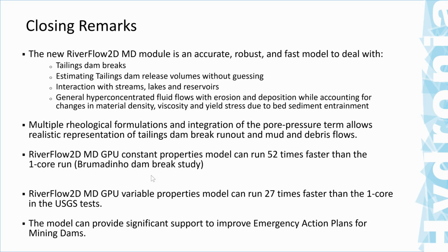You can use the model as a general model to simulate hyperconcentrated fluid flows that include erosion and deposition, and at the same time account for changes in material density, viscosity, and yield stress due to the sediment entrainment. And all of this is in a two-phase full two-dimensional modeling environment. You have multiple rheological formulations and integration of the pore pressure term.